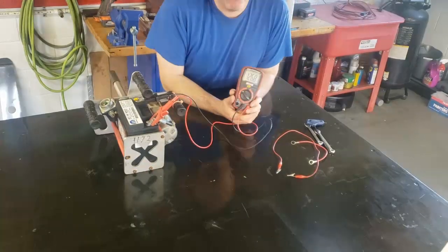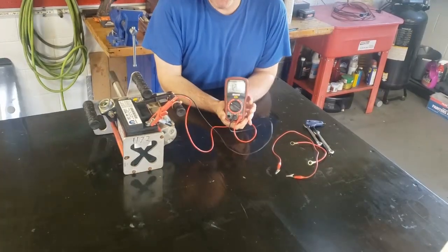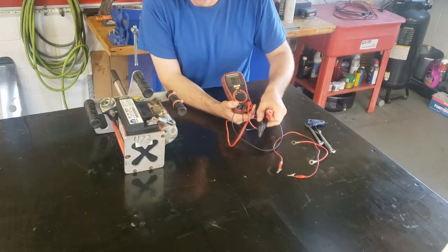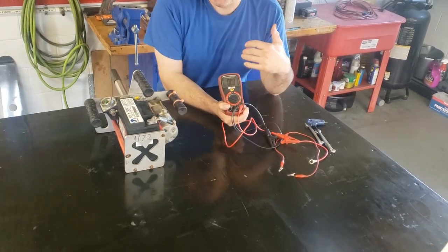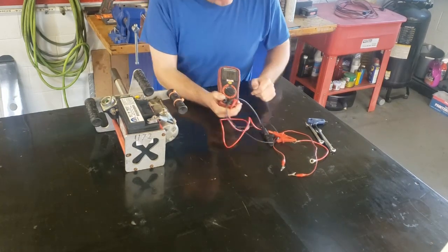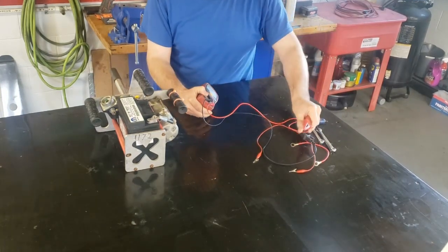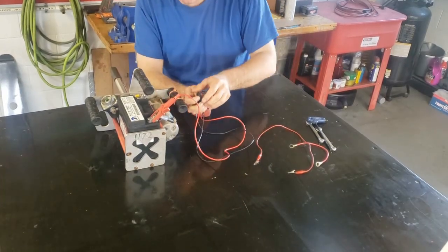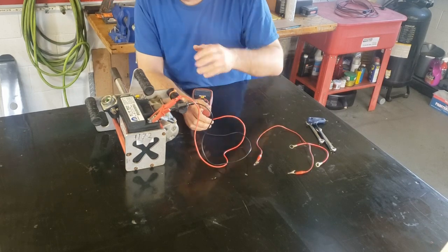Okay, so now we're going to do a voltage drop test. And what a voltage drop test is going to tell us is how much of this voltage is dropping, or actually are we losing, in this battery cable. In order to do that, we're going to connect our leads now to both ends of the same cable. One to the battery, one directed to the starter motor. The same thing we're going to be doing on the vehicle.